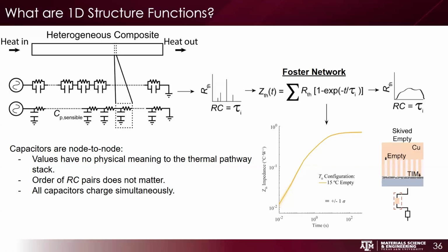More usefully, it's independent of the applied power. Once you normalize by power, the thermal rise scales accordingly. You have an LTI system, right? So not just initial temperature or ambient. You can change the ground point on the right-hand side, that's your ambient temperature, but you can also change the applied power. The transfer function is still the same. So Z thermal is your transfer function.